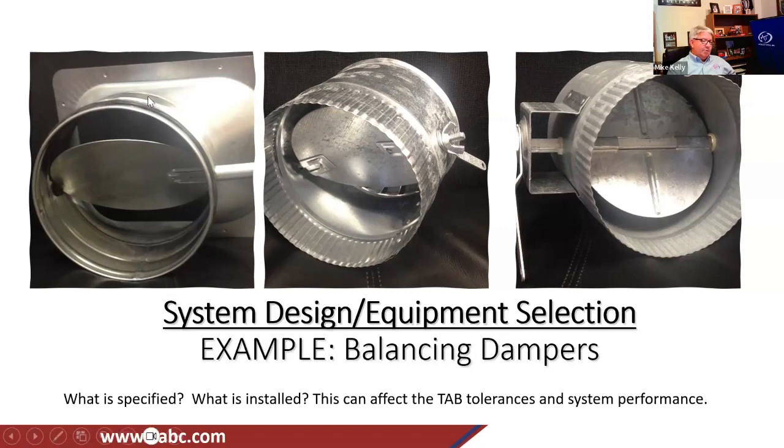They cut this round 8-inch hole, but if you notice the fitting here on this left picture has a flanged, almost conical shape. Well, if you put that round hole and then you put this large conical fitting, air blows by it like a Coke bottle, and it'll actually suck air in through that hole.